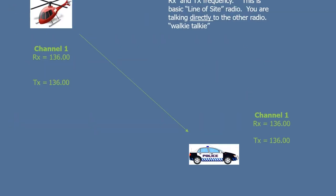So what is a simplex channel? A simplex channel is really basic line of sight radio. It is the radio that you are most used to seeing. I'm going to tune a frequency or I tune a channel and we're going to transmit and receive on the same channel. It's line of sight radio. Now we are talking land mobile radio. So line of sight might not be that very far. It might be 3 miles, it might be 20 miles. Depends on the topography, the area that you're in, hills, valleys, buildings, those types of things.